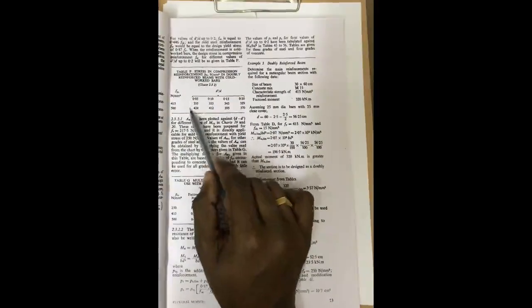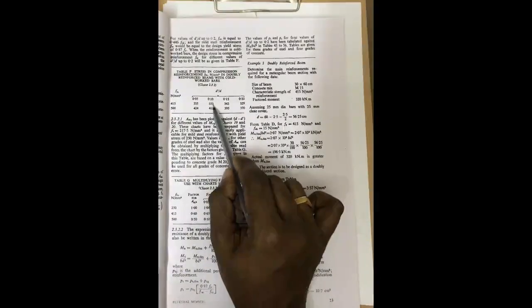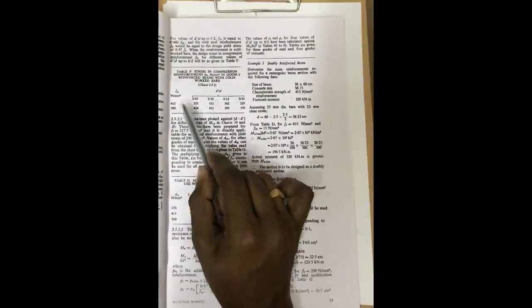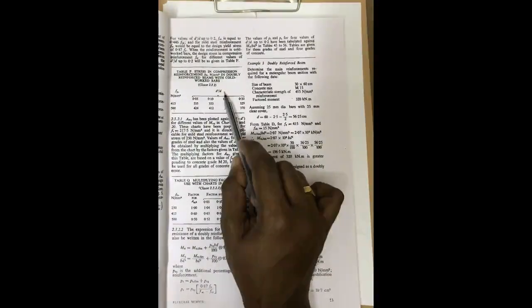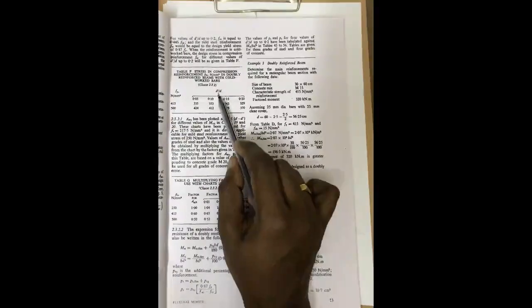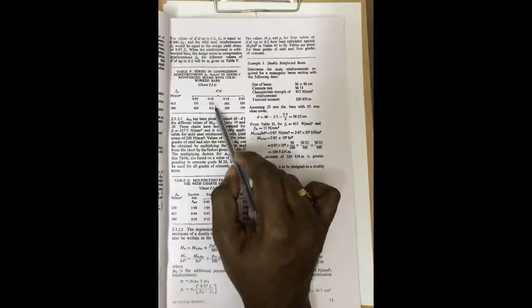Okay, so how do you take it? These are actually the Fsc values, and to choose a particular Fsc value, you need to know the grade of steel, as well as the value of the ratio d prime by d, d dash by d. You should know d prime and d. We have already defined these terms, and once you know this ratio, a suitable value may be chosen from the given table. So Fsc you will get like that,